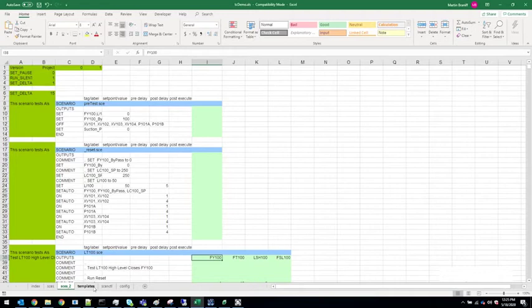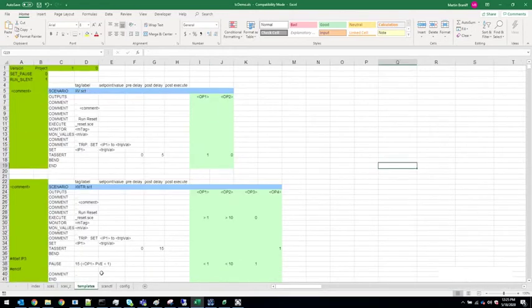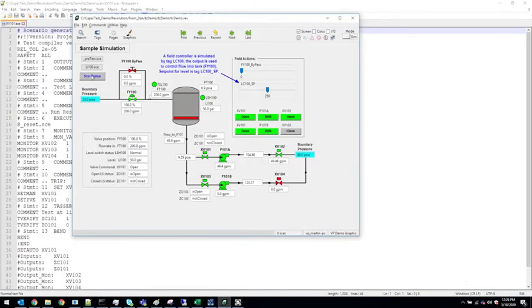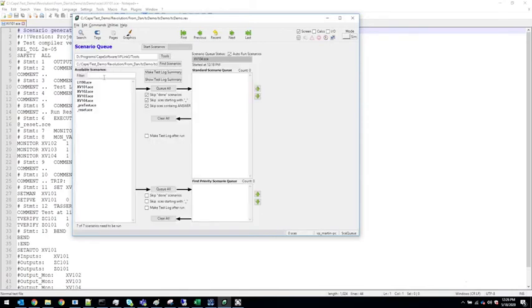The typical test plans can be put together using Excel, which provides an intuitive method of setting up the scenarios. These scenarios can be used to test 2 out of 3 failures, reset procedures and trip conditions, as well as many more situations. Once the Excel sheet has been put together, the user can then use Wood's proprietary test compiler module. This then converts the Excel template into a scenario file that can be used within VP-Link. The scenarios are executed and can be monitored from the LiveCode HMI.